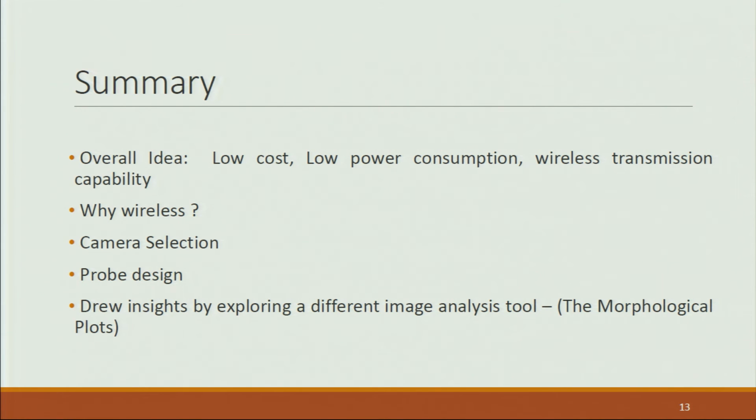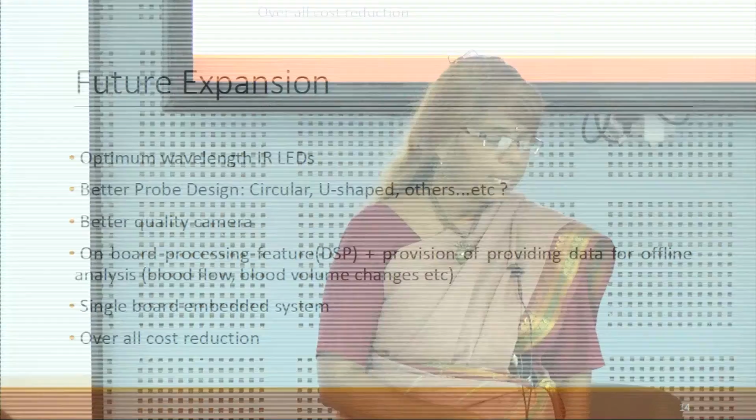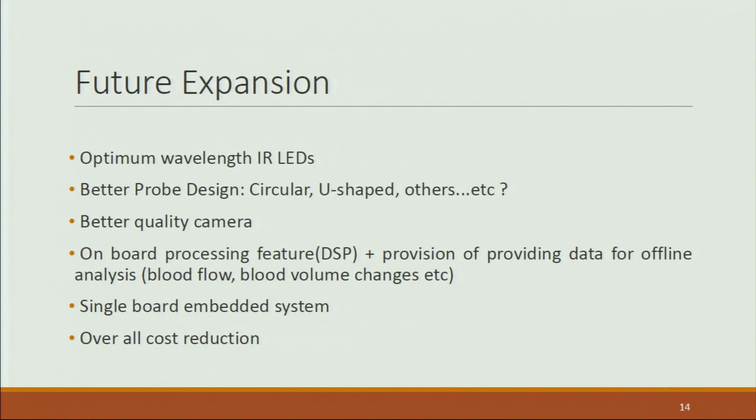And then the probe design, again we can use 2 LEDs or you can use a bunch of LEDs. Again you want to use a circle shape or U shape, T shape. We tried many, we don't show it all here. And then again you try various image analysis tools and then you come up with the one. So this is really a good project for students to learn more, not only image processing but also to know the hardware limitations and their capabilities.